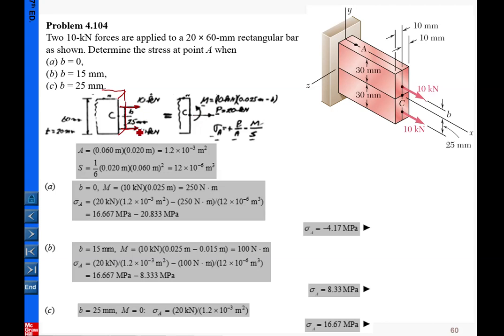So basically here, the total normal loading is equal to 20. And also with respect to the centroid here, the moment you can calculate is, okay, contributed by 10 with this arm, equal to these two terms, contributed by 10 with this distance b, and that comes to this and this term here. So the moment is equal to the two terms here.